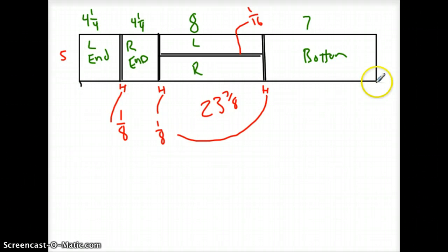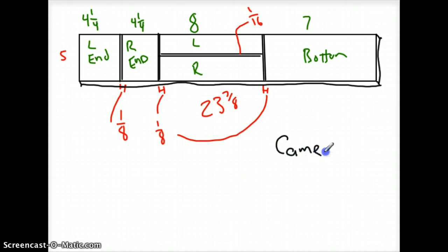So to turn on the 3-dimensional view, go up in the CAD program to the menu item called camera, pick the one called standard views, and pick the one called ISO.